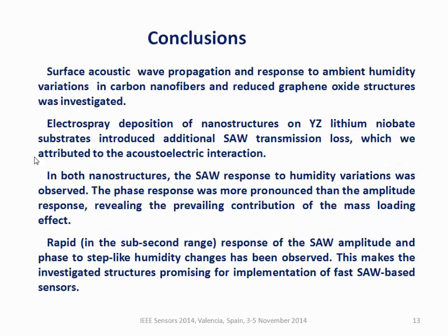So let me conclude that surface acoustic wave propagation and response time to humidity variations in carbon nanofibers and reduced graphene oxide structures was investigated. Electrospray deposition of nanostructures on YZ lithium niobate substrates introduced additional slow transmission loss, which we attributed to the acoustoelectric interaction.